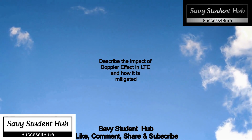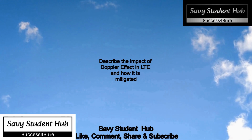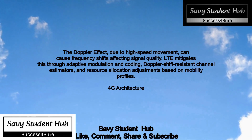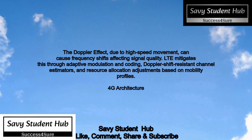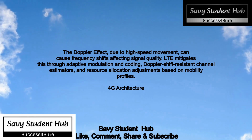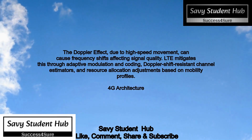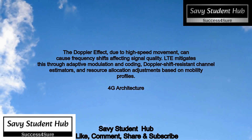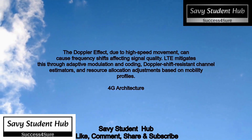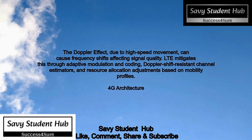Describe the impact of Doppler effect in LTE and how it is mitigated. The Doppler effect, due to high-speed movement, can cause frequency shifts affecting signal quality. LTE mitigates this through adaptive modulation and coding, Doppler shift-resistant channel estimators, and resource allocation adjustments based on mobility profiles.